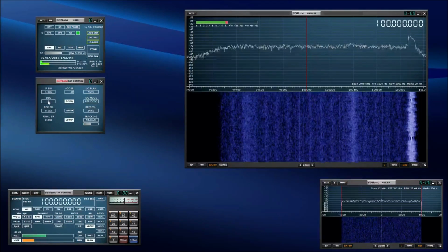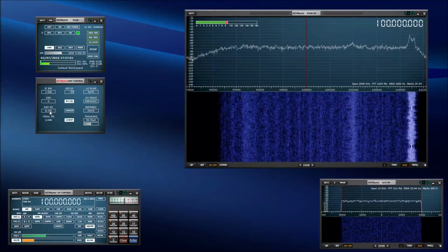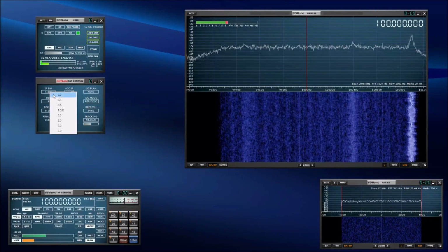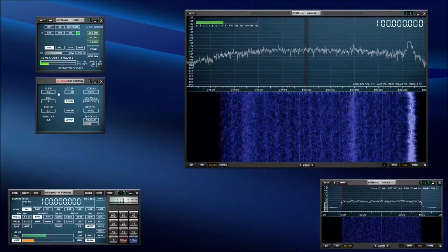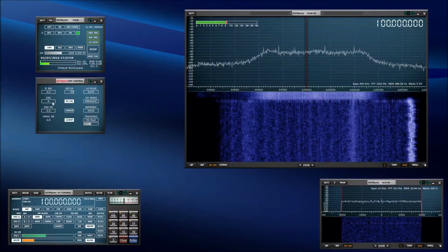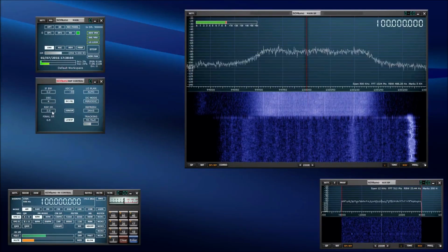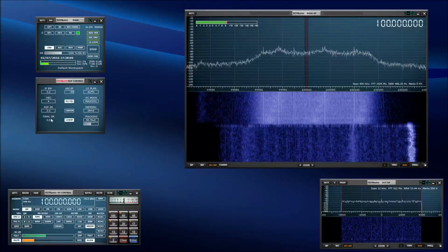These are all fixed. I can't change the decimation value or the sample rate here. If I specify 0.2 megahertz bandwidth, I still get a decimation of 4. The sample rate into the RSP is 2, and the final sample rate is a half.